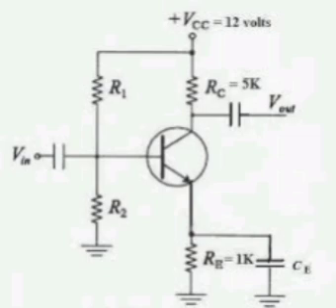MOSFET is in saturation. Then the equation is IDS equal to mu n Cox by 2 into W by L into Vgs minus Vt whole square. IDS equal to 0.2 by 2 into 2 minus 1 whole square milliamperes. IDS equal to 0.1 milliamperes. KCL: V0 minus 4 by 20K equal to IDS. V0 minus 4 by 20 equal to 0.1. V0 equal to 6 volts.